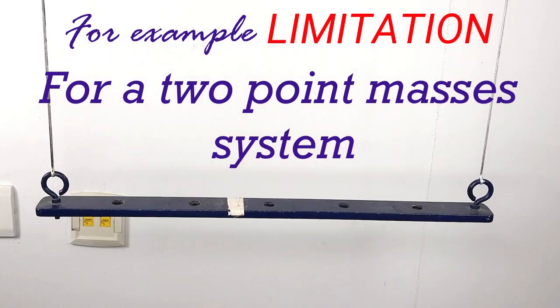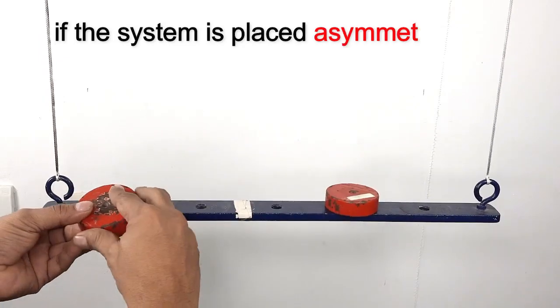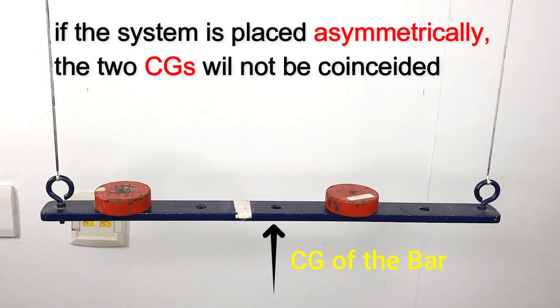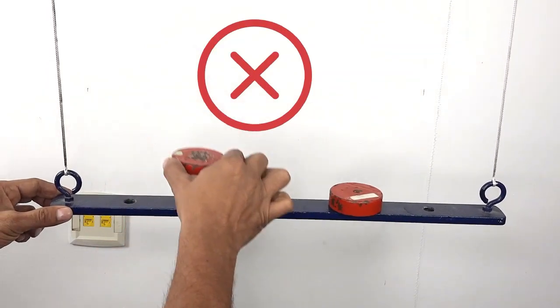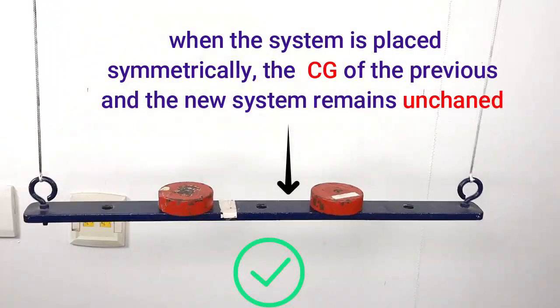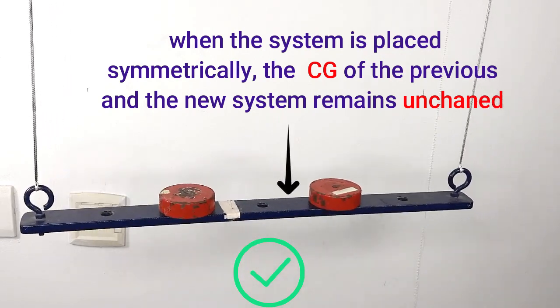For example, if I want to find the moment of inertia of a two-point mass system and I place it asymmetrically with respect to the center of mass of my base system, then during the oscillation the axis of rotation of the combined system will not match the previous case, and you will not be able to compare the two moments of inertia. That means this is the limitation of the bifilar suspension system.